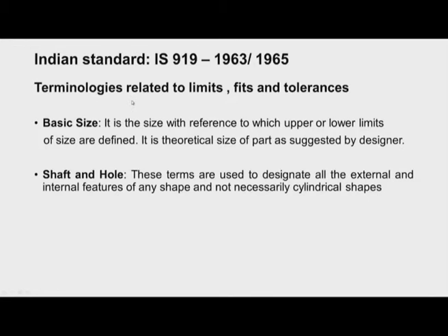Now, let us learn about some of the terminologies related to limits, fits and tolerances as per Indian standard IS 919. Now, we should understand what is the meaning of basic size. It is the size with reference to which upper and lower limits of the size are defined. It is the theoretical size of the part as suggested by the designer.